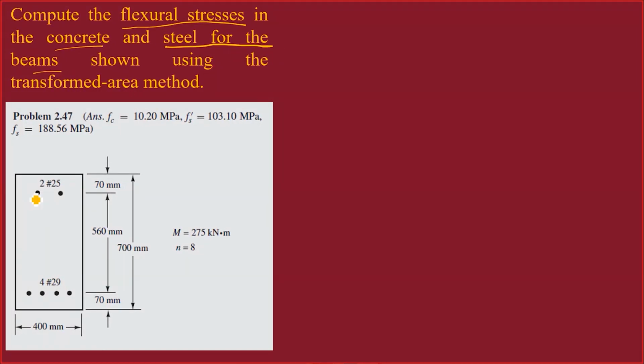We can see reinforcement at the top and reinforcement at the bottom. We are asked to compute the stresses individually: the stress in the extreme fiber in compression, the stress in these two bars in compression also, and of course the stress in the bar in tension.